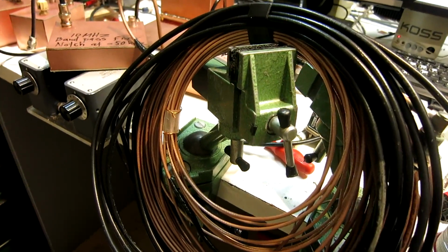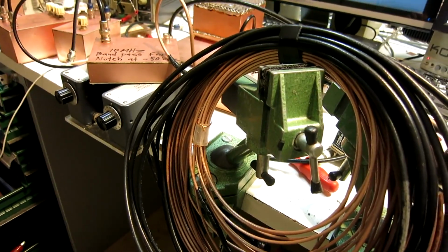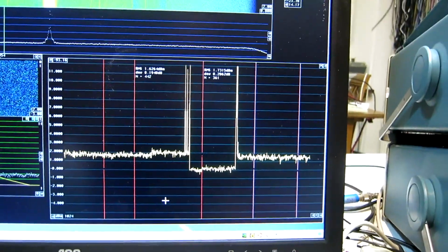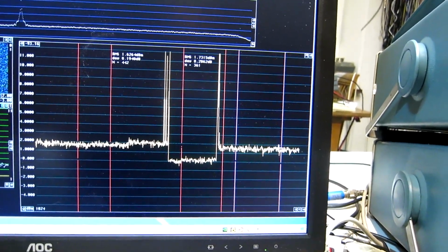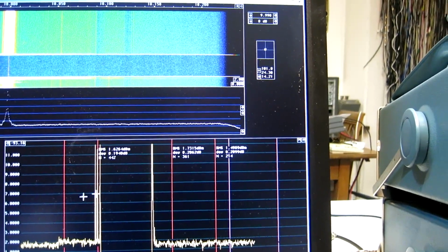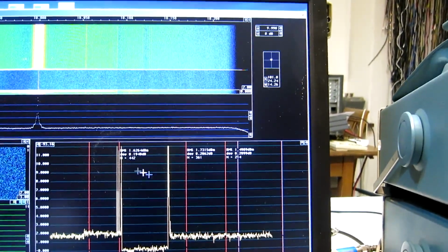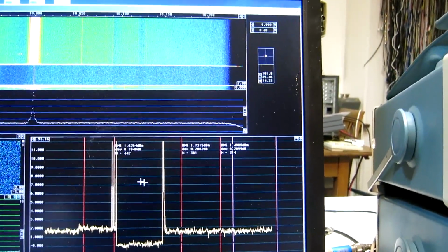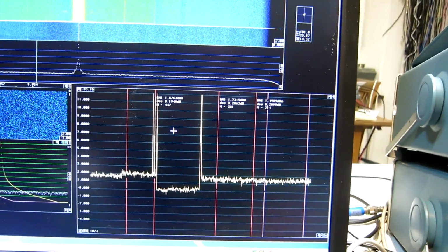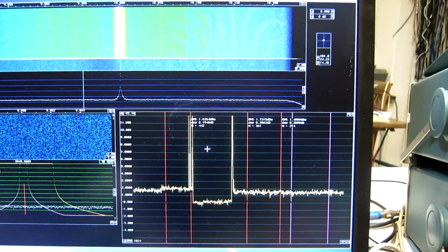Maybe that's just the difference in how much attenuation these attenuators give. This bunch of cables give quite accurately 3 decibels of attenuation here on 10 megahertz. And it looks like the noise floor is significantly lower. 1.49. That's 1.5. It's 0.1 dB below the small one and 2.2 dB below the big 3 dB attenuator. I think I'm seeing the noise of the small resistors inside these attenuators.